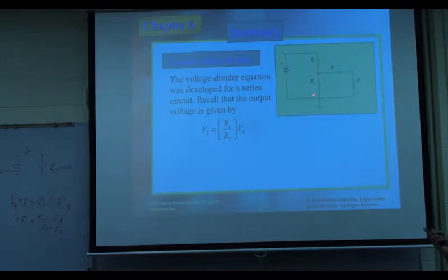If you compare this loaded voltage divider, it is not exactly the same as we discussed before. Before it was a series circuit. This one is a combinational circuit. This is not series. It's not parallel. This load is parallel with R2. So how do we find the voltage here? I still want the voltage on R2. That is the purpose of a voltage divider. But in this case, it is loaded. So how do we find it? This formula won't work anymore, because in this case we do not consider R3, or R3 equals infinity. It's not there.